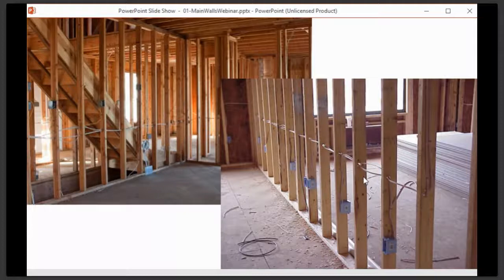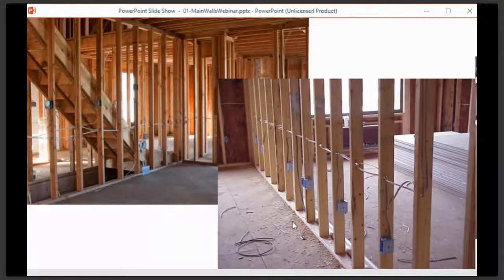Now, I should mention here as well, I do know that obviously with these hollow masonry walls, electrical wire can be run through the hollow, but that will be something that you would need to investigate as to how you would do that. But either way, you're always going to have to make sure that you know exactly where you want your fittings installed, so that they can be done before the structural finishes are put into place.